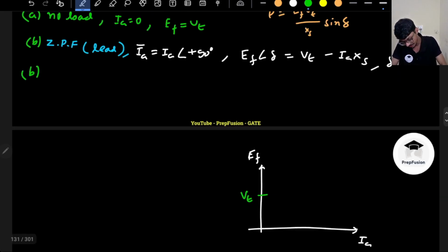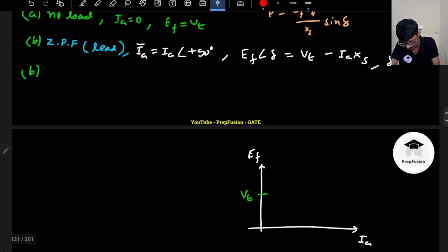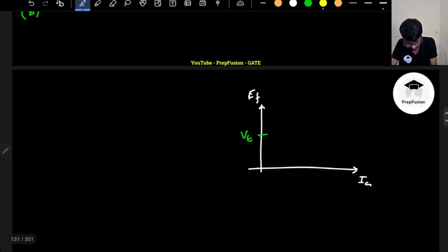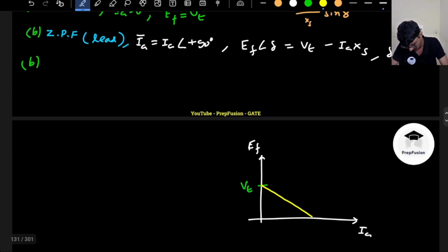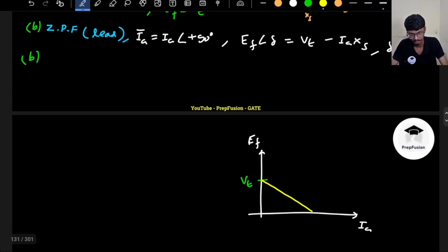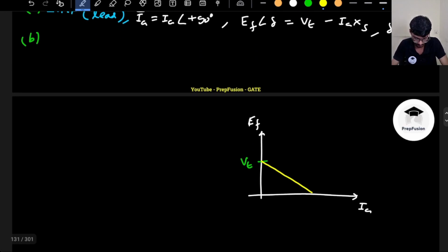Okay. Now I see the voltage is linearly reducing, so now it will reduce linearly and not increase. So now the short circuit current will happen due to the leading load, not due to the lagging load. So the bottom side will now be the leading load. So this will be 0 power factor leading. Am I correct here? Yes, I'm correct. 0 power factor leading.